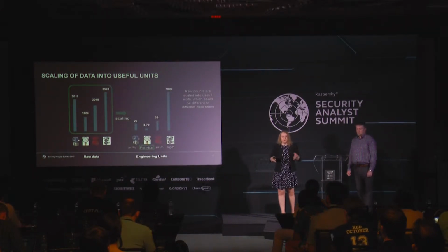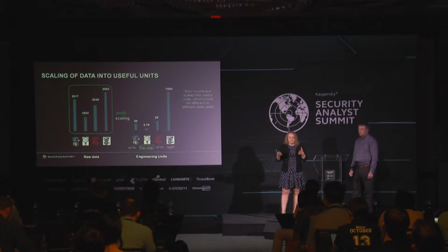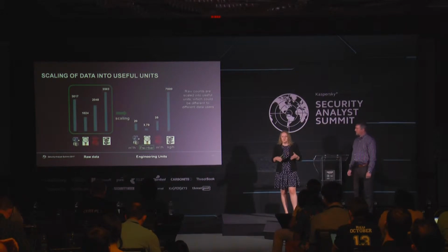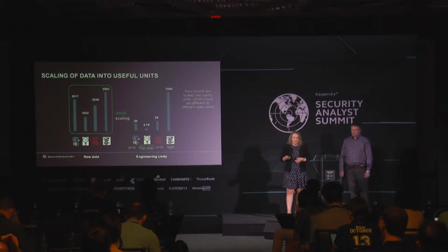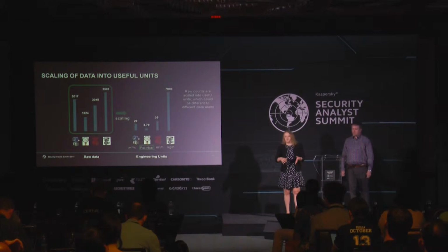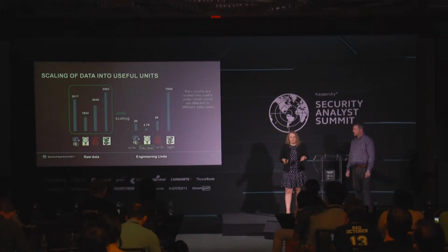Eventually, these raw bit counts will be translated into engineering units, but not necessarily the same units in which it was measured, because the operator will have different requirements, and through formulas they can be translated into completely different units. Depending on the configuration of the system and the industry, for example process control or substations, sometimes the raw data will be scaled already at the HMI and sometimes on the controller. So what the attacker will see in the packet could be both engineering units and bit counts. And we will see that in the substation, you will typically see those no-name counts, which tell nothing to the attacker.